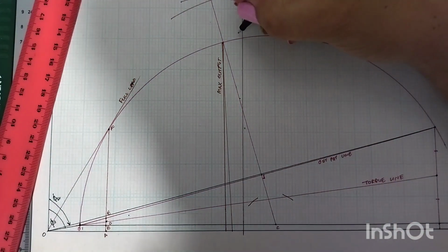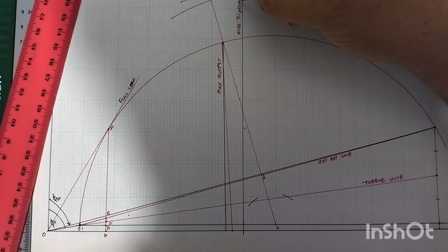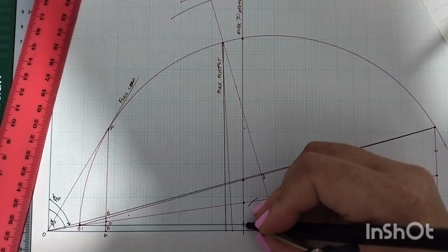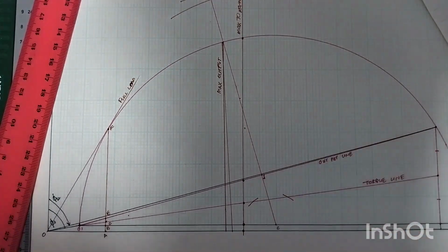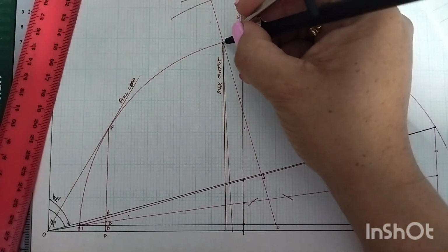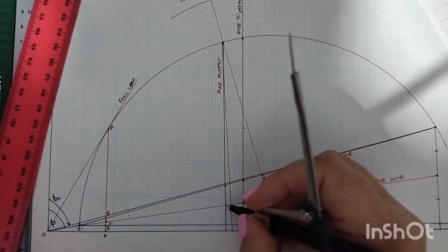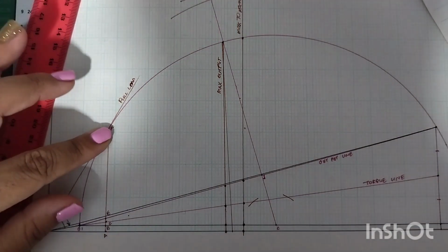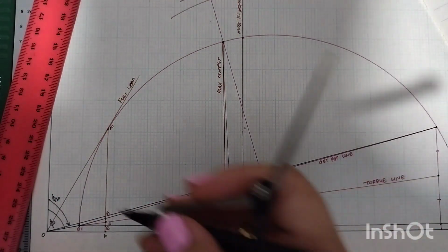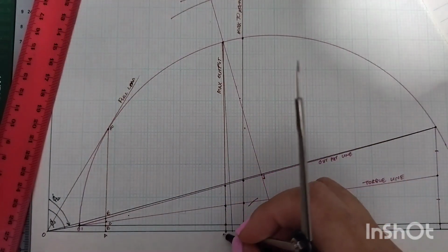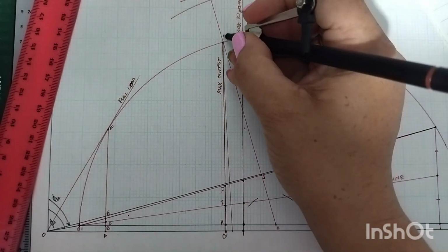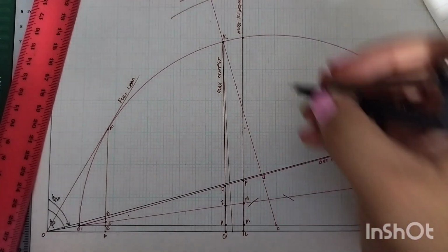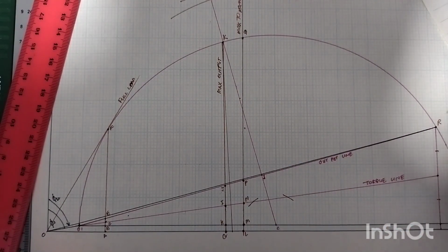I'm going to make a marking on the perimeter of your circle and on your output line, on your torque line, and on your horizontal axis, both the new horizontal axis, the diameter of your circle, and also your original horizontal axis. The distance between your original horizontal axis and the diameter of your circle represents your constant losses. The distance between that axis and your torque line is your stator copper losses. Remember, stator out is rotor in. Between your torque line and your output line for any load is your rotor copper losses. And beyond that, from your output line to the perimeter of your circle is your output.